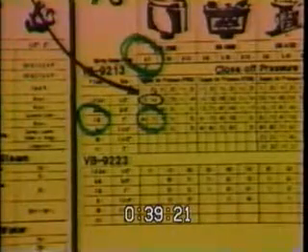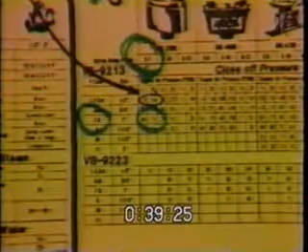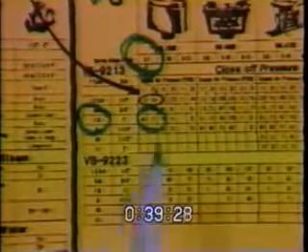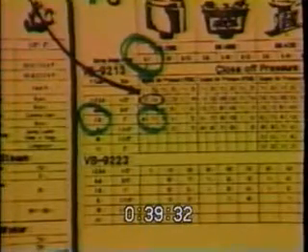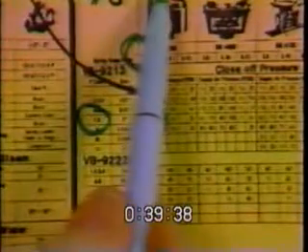Now, it needs to be greater than the close-off pressure rating that you needed. We needed a close-off pressure rating of 10. This has a rating of 75, therefore it's quite adequate to close off against the flow. Therefore, we're going to take this series of actuators, which in our example is series 200.